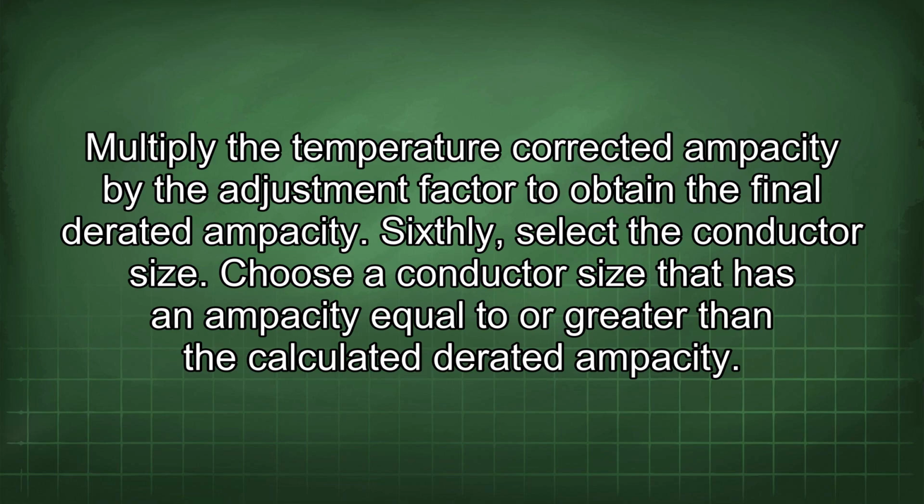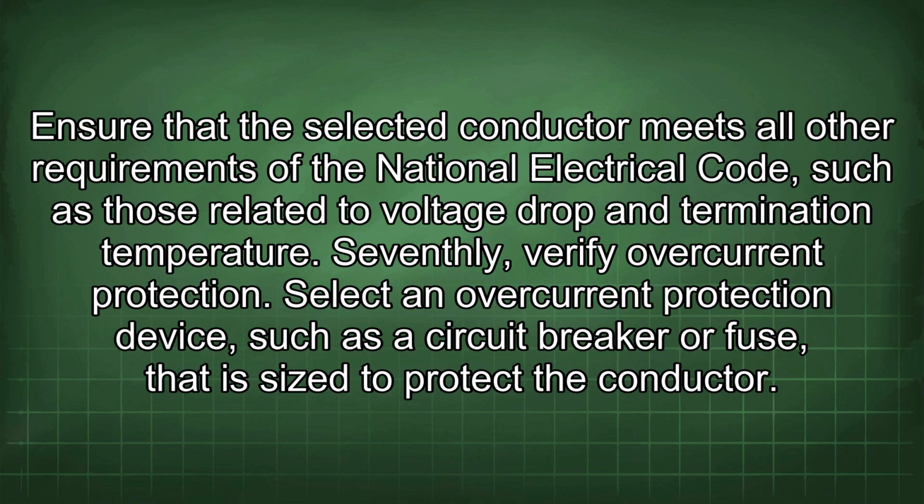Sixthly, select the conductor size. Choose a conductor size that has an ampacity equal to or greater than the calculated derated ampacity. Ensure that the selected conductor meets all other requirements of the National Electrical Code, such as those related to voltage drop and termination temperature.